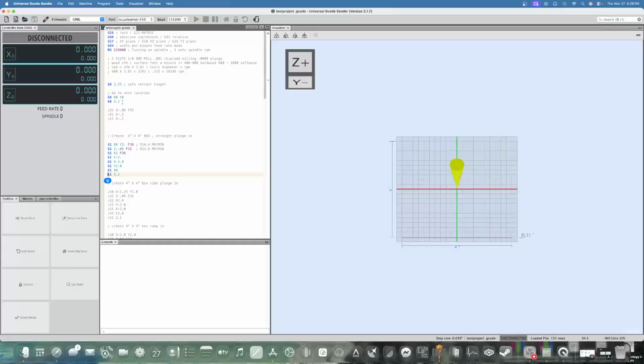Or, if you touch off the top, and this side over here, because you ain't machined it yet, it's a little bit higher where you just wrap it into the part. You can damage tooling and whatnot. So it's always a good idea to leave the Z above when you're doing rapid.